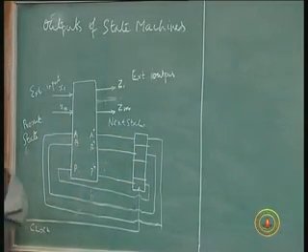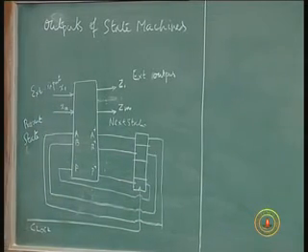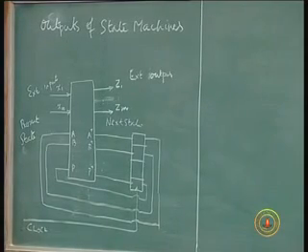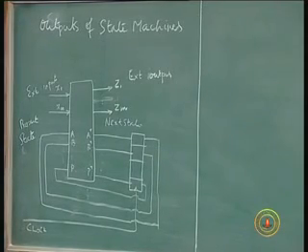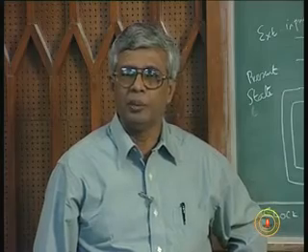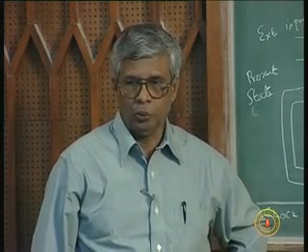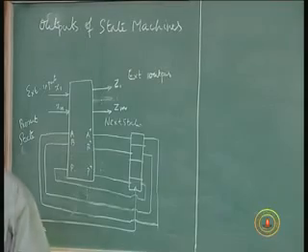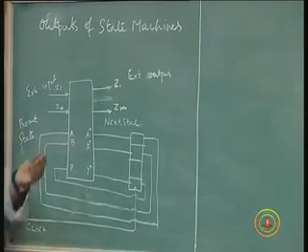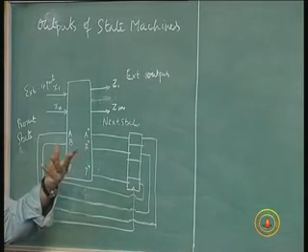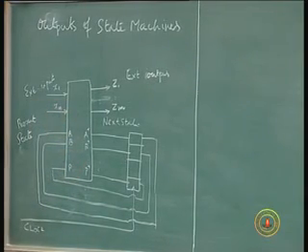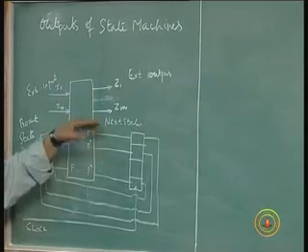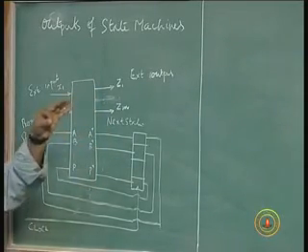Now, when we are drawing the state graph, we have to accommodate for these outputs, which we have not done specifically. In the state graphs we have drawn so far, we have not taken into account these outputs, which can be external outputs. Of course, for outputs which are state variables themselves, we don't have to have special provision in the state graph, because the state information is anyway there, and that information also acts as the output information. But for outputs external to the state variables, we have not so far made any provision.